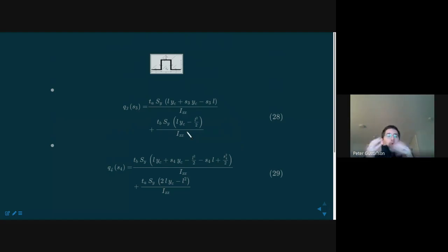All right, so before we move on to the next thing, let me summarize what we have so far. We have calculated shear flow in this cross section. We have a resultant load. That's the total load on the cross section. And from the total load, we've calculated the shear flows. And got to keep in mind, what is shear flow? Shear flow is shear stress times thickness.